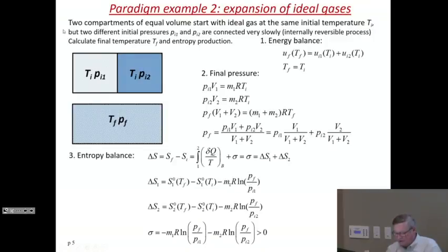Well, these temperatures, final and initial, are equal. We had that for conservation of energy. So these two are the same, and these two are the same. They just cancel out. And you have delta S1 is minus M1R ln PF over PI, and the same for the two. And the entropy then is this, and again, the minus sign here comes from here.